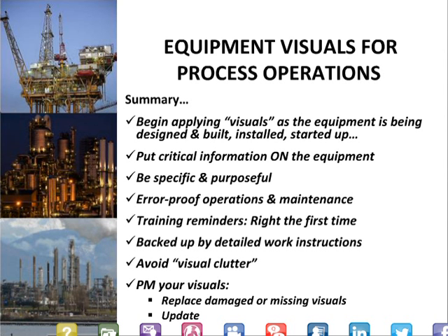So a number of manufacturers are applying these things to their equipment at customers' request, to open up the guards with Lexan panels or polycarbonate panels, to label all the lube points. Again, this is a very collaborative effort to make sure that they use the same type of lube identification, point identification, and numbering sequences that you do in your plant. So we're seeing that the new equipment hits the ground and it's ready to go. But you can also do it during installation, startup, and commissioning.